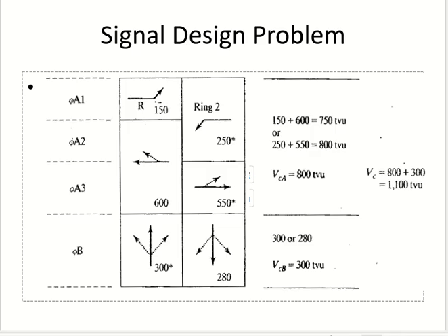For each movement, they have given us the volume, and the volume is in equal terms. So you can now compare directly. What we have to do is find out the total critical volume. I'll look at each phase, because there are multiple movements in each phase, and I'll pick one of them as my critical volume.